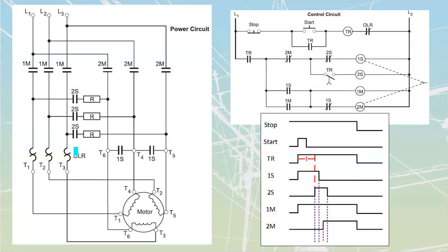And I've even redrawn this thing, so that we can see transition to transition just what those connections actually are. A couple things to note. We've only got one timing relay that is going to have one set of timed contacts over here. It's normally open time to close. And when that timing finishes, I've got a bunch of purple lines over here. The purple lines are just indicative of the fact that we have interlocks. We're going to go from one to the next, to the next, to the next. It's going to be the sequence of controls that we need to see happen as we're going through.